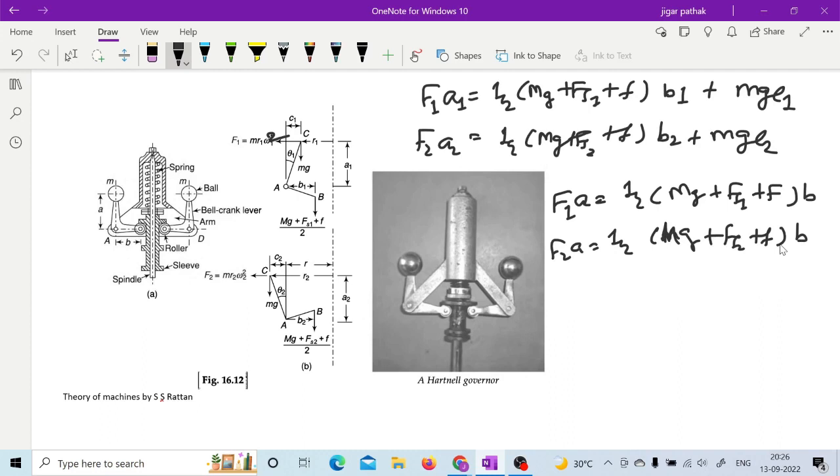So now having these two equations, if you take subtraction, then this fs2 minus fs1 can be written as f2 minus f1 into 2a by b, right? This fs2 and fs1 are spring force. So spring force is nothing but whatever that stiffness of the spring and the deflection.